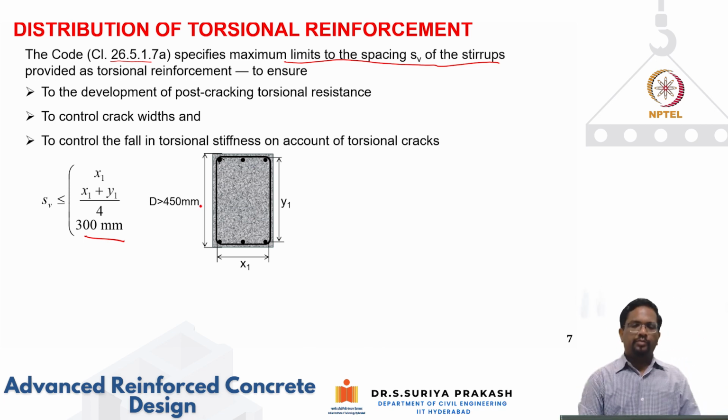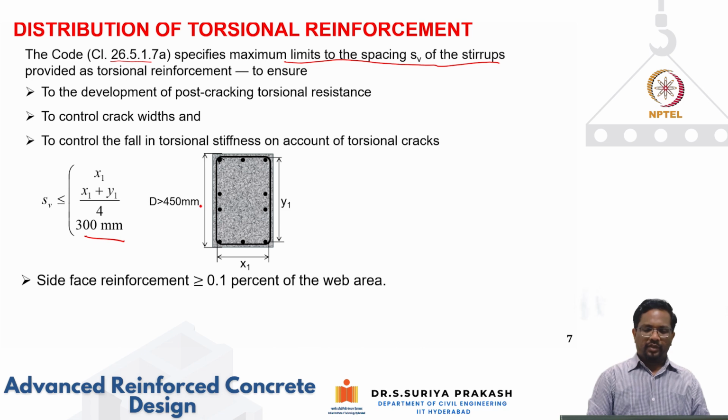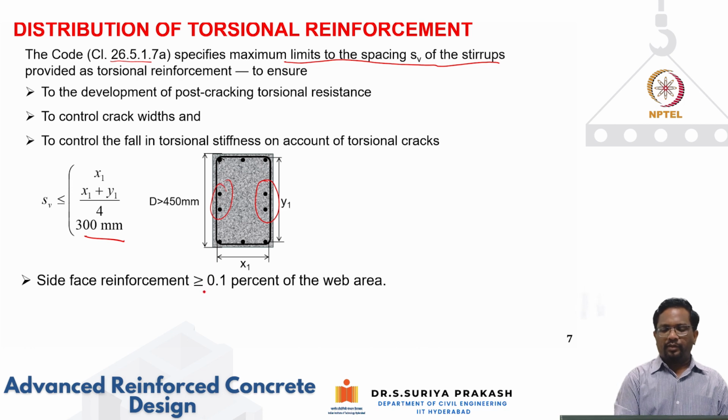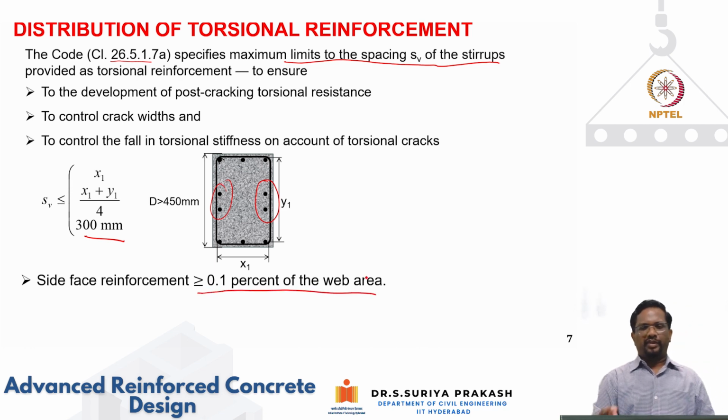And when D becomes more than 450 millimeter, then we also need to put some side face reinforcement. What is the amount of the side face reinforcement? It is actually 0.1% of the web area, very limited reinforcement.